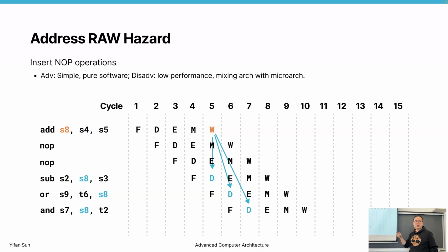So it puts more constraints on the microarchitecture design. If this is the architecture level definition, we basically have no way to define a 20-stage pipeline instruction. If we design a 20-stage pipeline, then this optimization will not work. Okay, so this design mixed architecture with microarchitecture and limits the flexibility of designing microarchitectures. So we really want to have a clean minimum architecture design so that we can keep both the compiler and the microarchitecture flexible. Okay, so those are the problems of knobs.